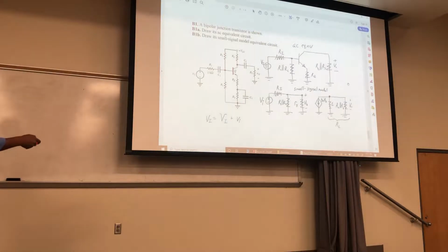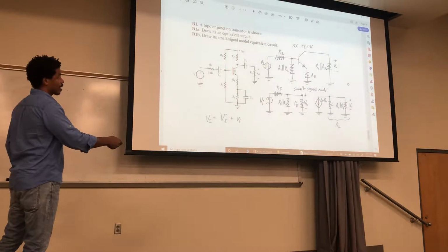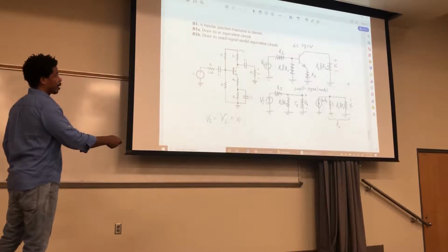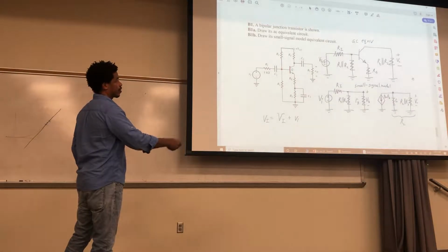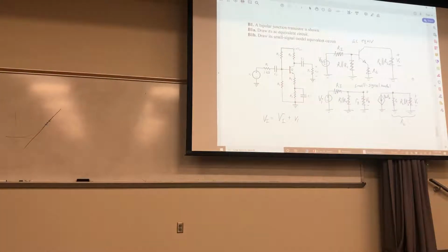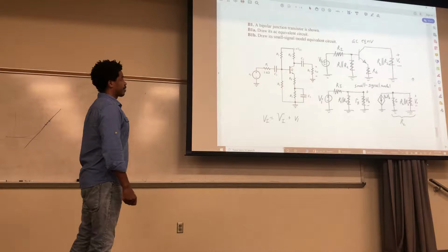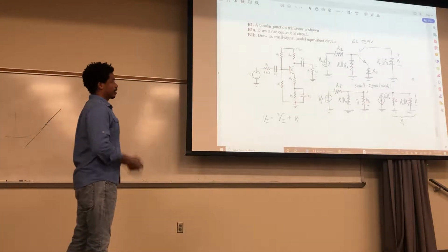But if we go to small signal analysis, where you're only perturbing a very small amount around there, then you can say my whole thing is actually just this element right here, and that is a linear element, not a nonlinear one. The current is proportional to the voltage by this transconductance gm, so a linear line right there. You're still only oscillating around this point, but you're going to model it as a nice linear model. That's the main reason for doing that, though there are other approximations you're making too. But that's a small signal model right there.